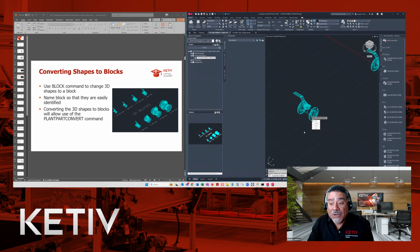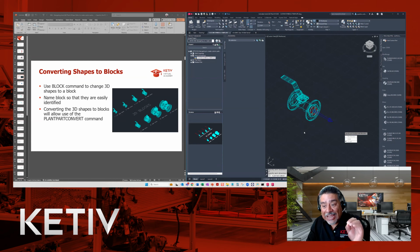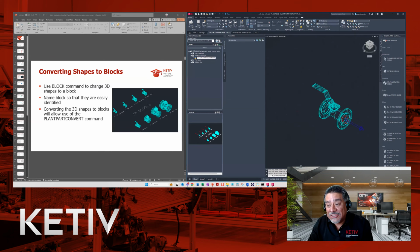So I need to add a port, and I want it to be on one side over here and one side over here. So I'm just going to select the center here and then pull it away. And you can see that it does add that port connection by giving me this glyph definition here. And it asks me if I want to accept it or flip the direction. I'm going to go ahead and accept that. And then it's going to ask me if I want to add, delete, or move, or just get out of it at this point. I need to add another one because I need one on the other side.